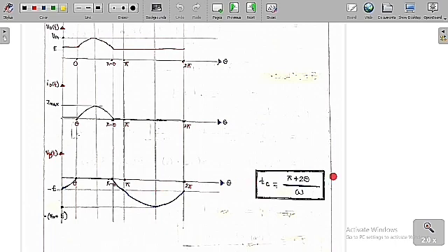So therefore, pi plus 2 theta divided by the overall angle omega, you are going to get the circuit turn-off time. So for this amount of time the reverse voltage across the diode is going to occur, which is tc equal to pi plus 2 theta by omega. So this is the circuit turn-off time of the diode.